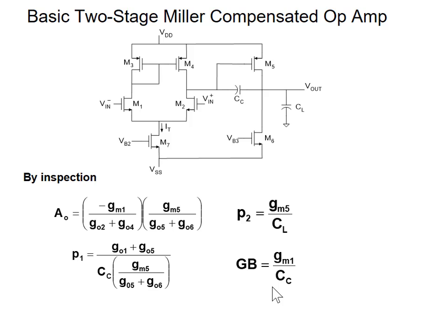When you compensate the structures, you compensate for poles, so feedback poles. So we've got the poles and feedback structure. So this will pretty much allow us to see to it that we've got it between 45 and 90 degrees. But I don't quite have the transfer function right. Does that make sense? Yeah. So right now I look at it as a 2-pole transfer function. There's 1 zero in there as well. So ideally that will give you a 90 degrees phase margin.